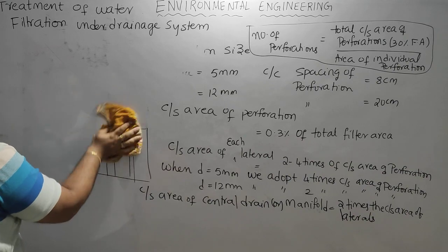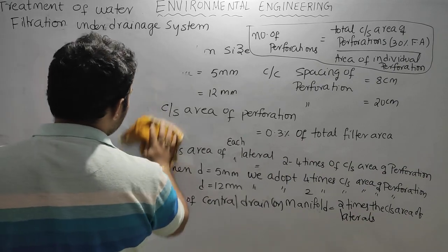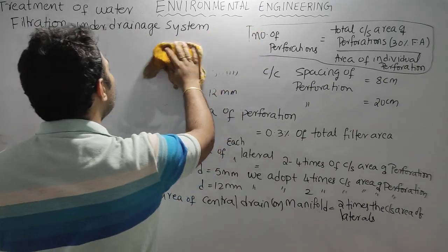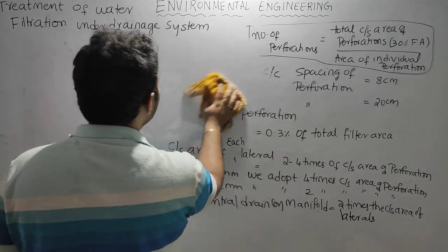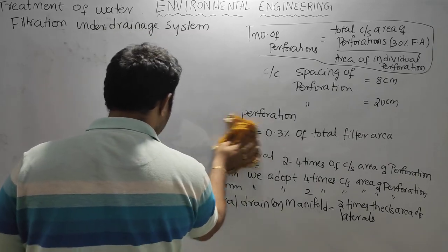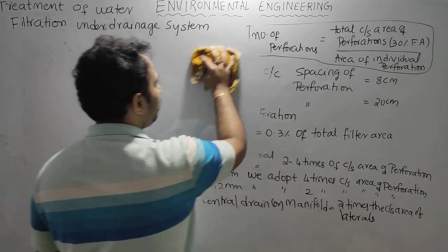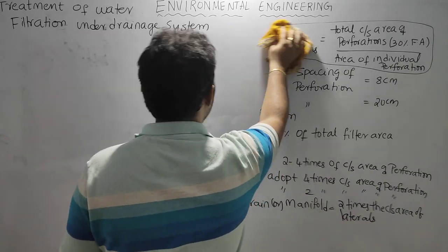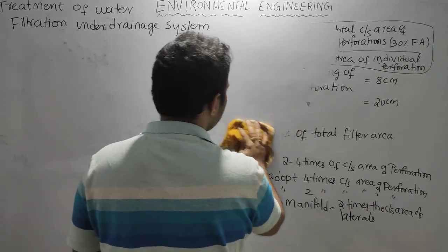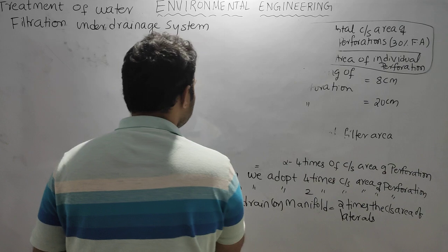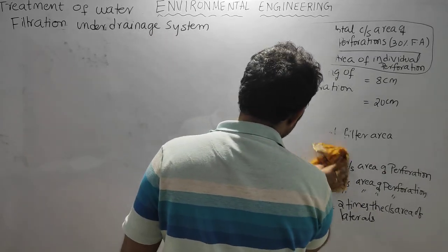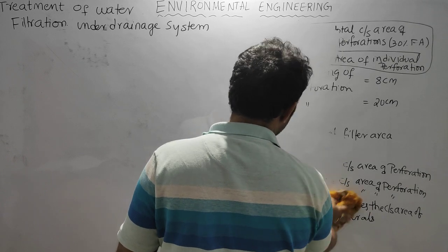If you are sending backwashing water, that means the water will move through the sand filter media with high velocity or with high pressure. Here we are sending the water for backwashing through the sand media either by high velocity or by high pressure. During this process, the sand bed faces some thrust from the bottom.